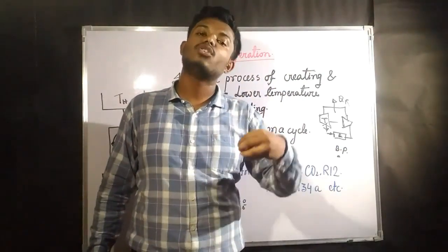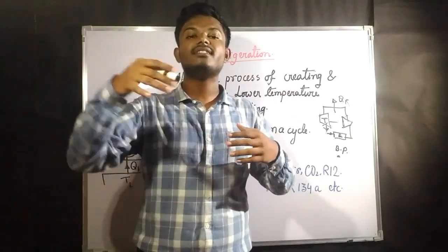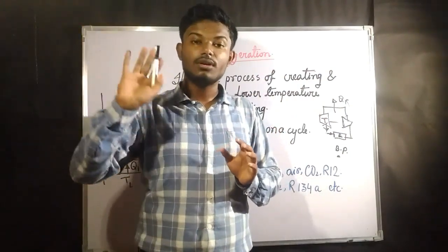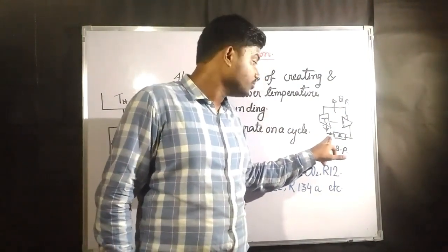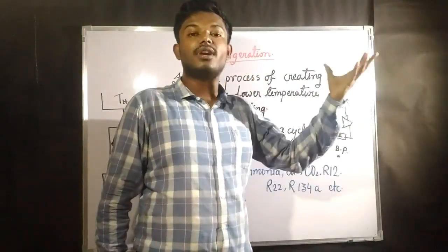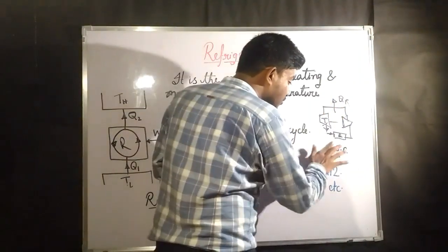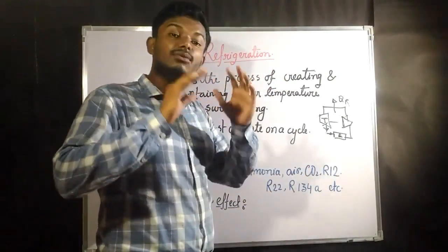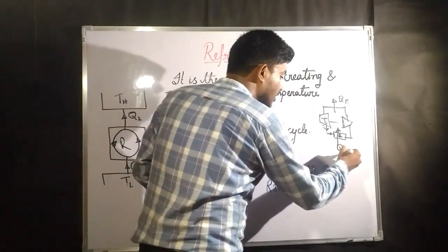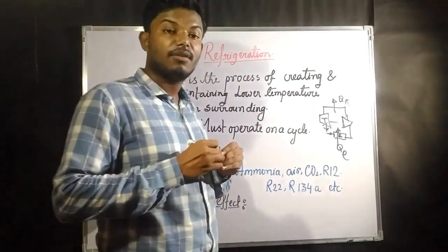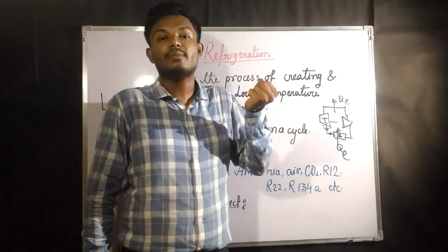At 10 degrees centigrade, automatically it evaporates or boils. Boiling means the complete liquid is now converted to vapor. So the substance which we are going to use will automatically evaporate at 10 degrees centigrade only. Now due to this evaporation, what will happen? During any phase change process, there is some latent heat involved. So during this evaporation process, it takes out the latent heat of evaporation.